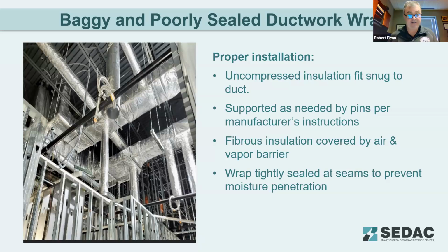It's not cut into the insulation, or the insulation is around the hangers. The system itself is completely 100% insulated, with the hanger support underneath it, outside the system. It's tight, but it's not too tight, reducing the R factor. And you can also see that the round ductwork coming off of it is sealed tightly, and the ductwork going into the ceiling as well. Very, very nice job there.